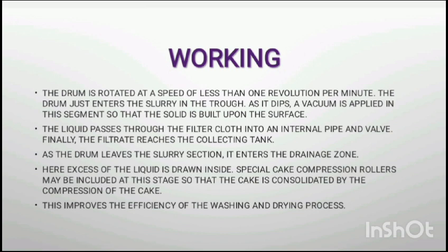As the drum leaves the slurry section, it enters the drainage zone. Here, excess of the liquid is drawn inside. Special cake compression rollers may be included at this stage so that the cake is consolidated by the compression of the cake. This improves the efficiency of the washing and drying process.